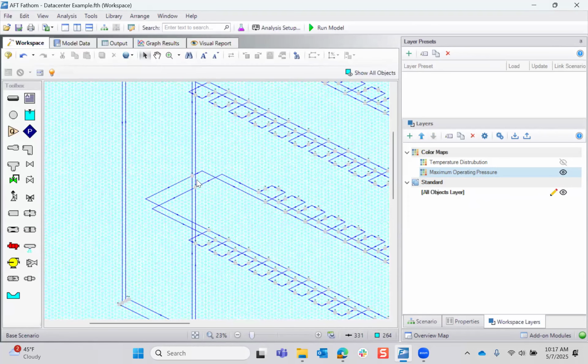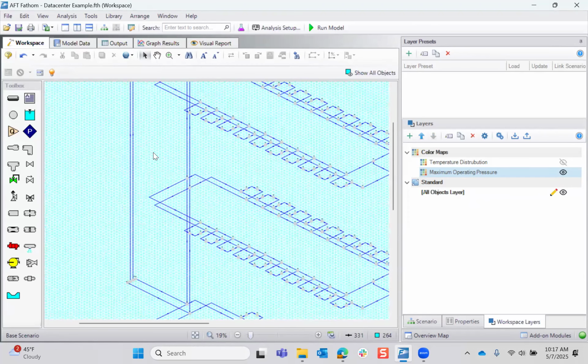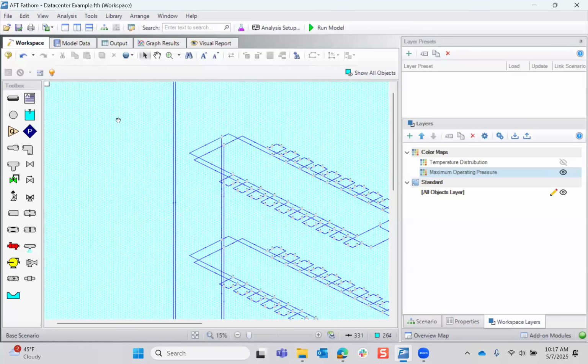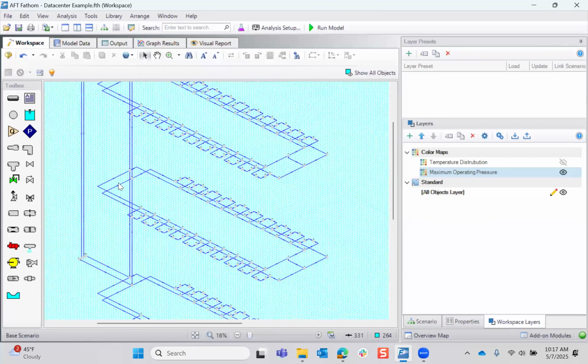This model was fairly low pressure throughout its running, so I never needed to worry about that, which is a good thing because in a lot of data centers, if you're getting close to that max operating pressure, you're putting a lot of stress on your flanges. It can cause more frequent leaks in the system, which in a data center is a big no-no.